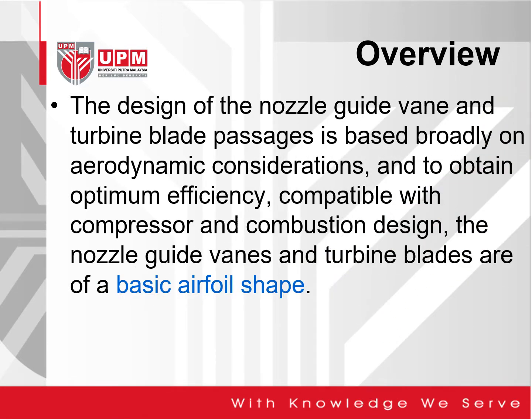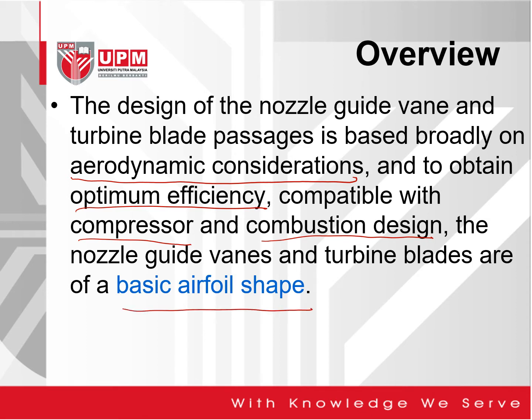Now, the design of the nozzle guide vane and turbine blade passages is based broadly on aerodynamic considerations. To obtain the optimum efficiency compatible with the compressor and combustion design, the nozzle guide vanes and turbine blades are of a basic airfoil shape. Later we will look at how the nozzle guide vane looks like.